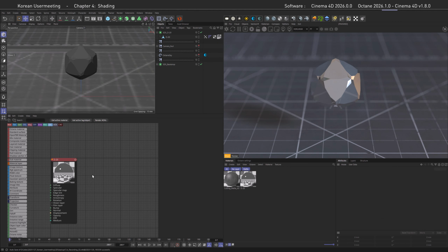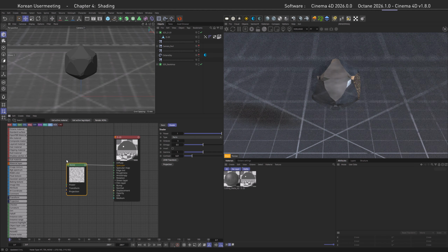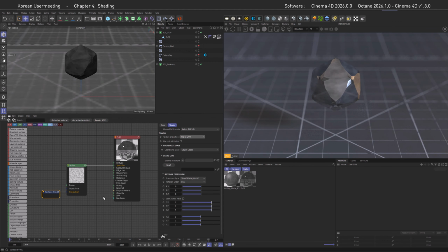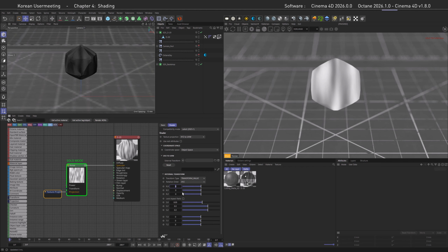As you've seen in the beginning of the video, we want to create some light play in the material, so let's bring out a noise into the specular, turn on snapping, and then get a projection going. Set the projection to XYZ to UVW, my favorite, then go with values 0.05, 0.3 and 0.3 on the X, Y and Z axis to make the noise smaller and squish it more together. Then go with an omega of 0.25 to make it less rough, and a contrast of 2 to give it more contrast. And as it looks a little bit boring, let's also add some angles to make it run through the object in a more interesting way.